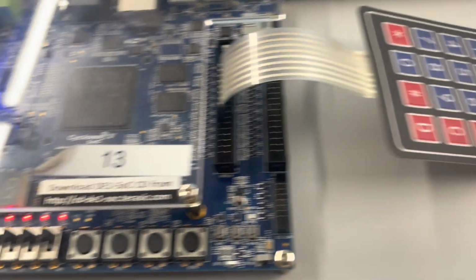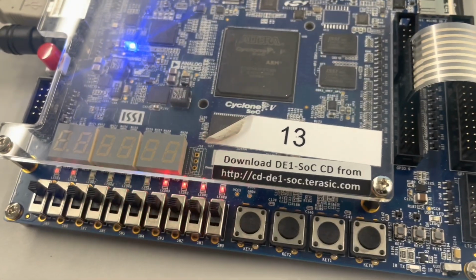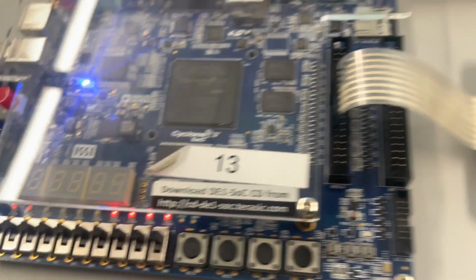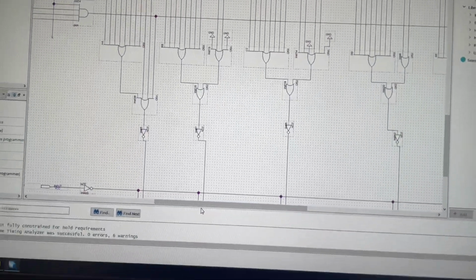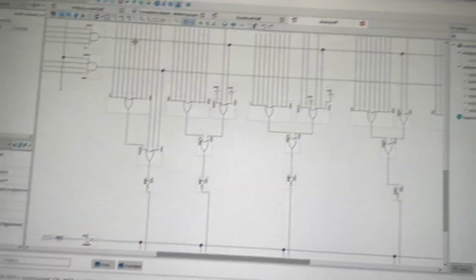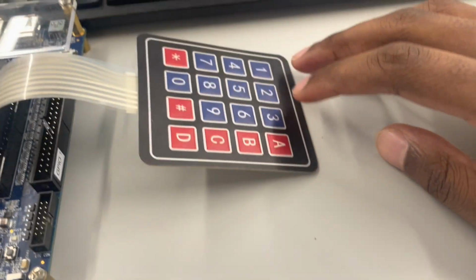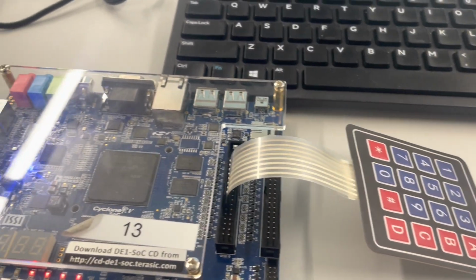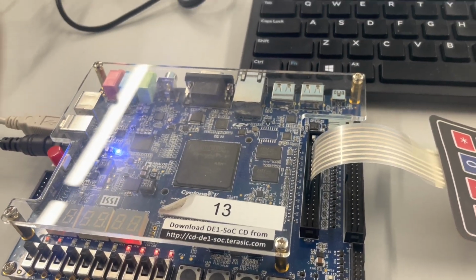Another bug I was unable to fix is the same row, which will be 2, and then if we press A, it will switch. So try to do 2 and A at the same time. Those will turn off, and that is due to the way the entire circuit is designed. This row will no longer become low as we needed at the beginning. This needs to become low to go. The row will no longer be low if 2 buttons are pressed in the same row. So it's impossible to display 2 buttons in the same row. However, 2 in different rows, different columns are easy. 2 on the same column, 2 rows apart, gets a little bit more difficult.